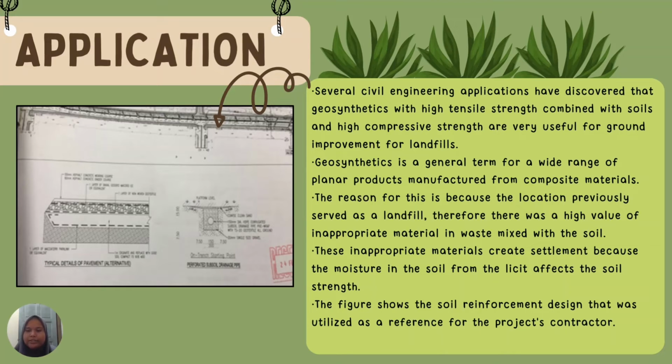At the landfill, there was a high value of inappropriate material. When waste is mixed with the soil, it will create settlement because of the moisture content in the soil from the leachate that affects the soil strength. This figure shows the soil reinforcement design as a reference for a contractor at the site.